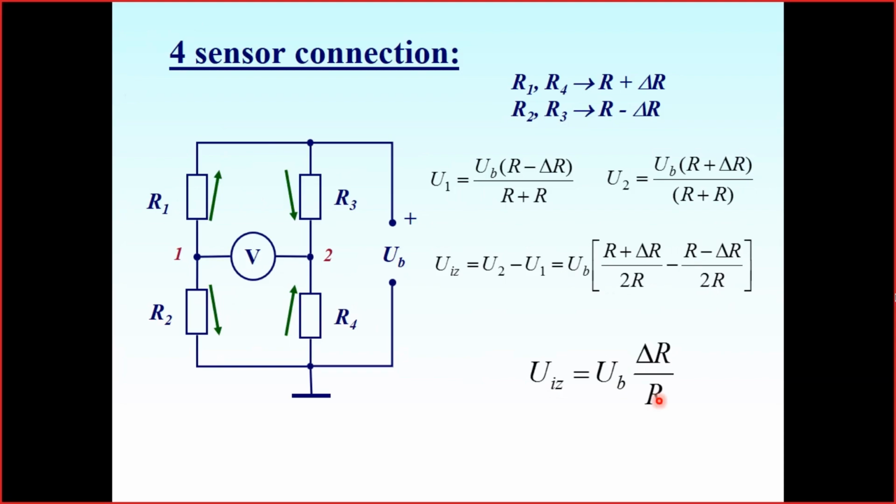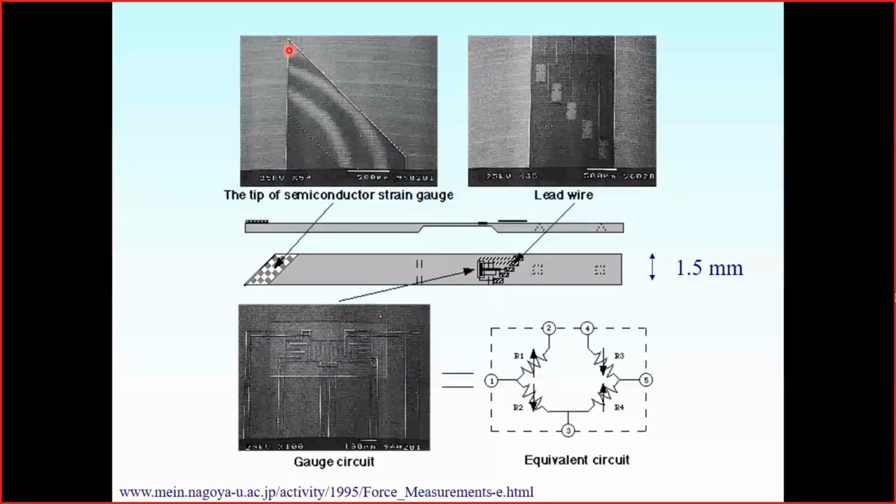So the force sensor connection peculiarity is that it is not nonlinear, so we do not need to neglect anything. They are quite linear and work very well. For this gauge, one more thing, please take a look. When we bend it to one side, the sensors on the top will be stretched and the bottom will be compressed. And the next time, they change polarity and measure in the opposite direction.